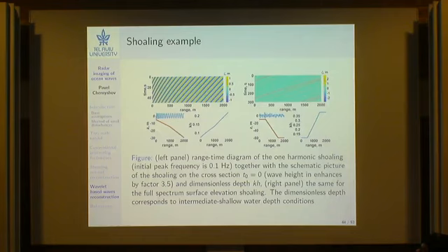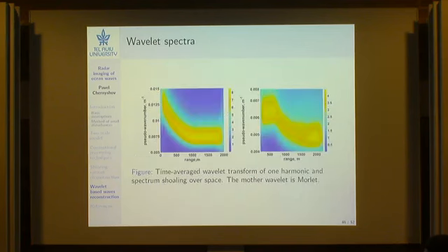Oh, I see. But the nice idea here also, I need to mention this. If you look at this wavelet spectrum, and if you can trace the peak K, or in this case, this is the only one K, you can reconstruct the bathymetry. Because you do know the dispersion relation, omega doesn't change, and you can solve for H. Yeah. This is maybe a topic for the next paper. Okay, thank you for attention.